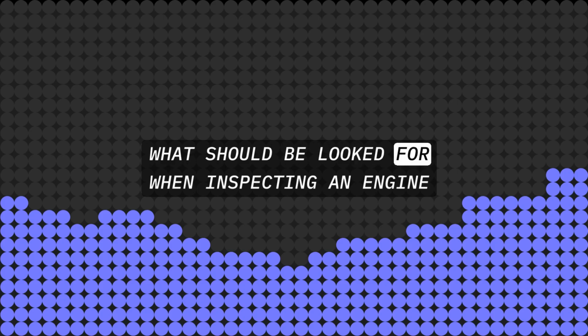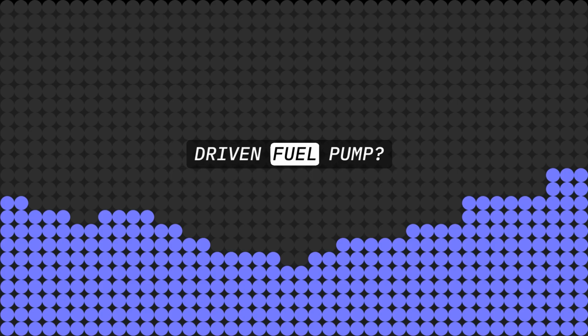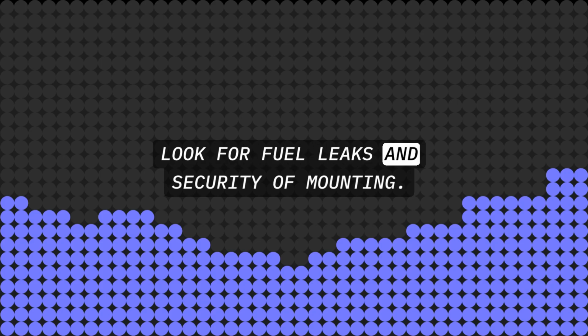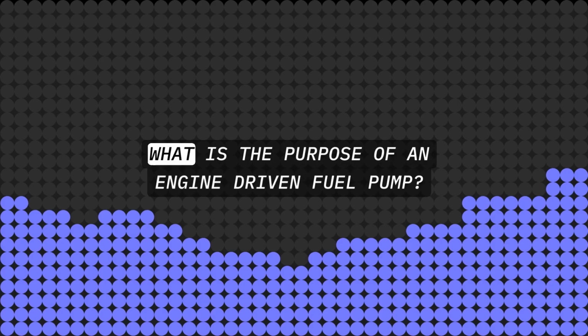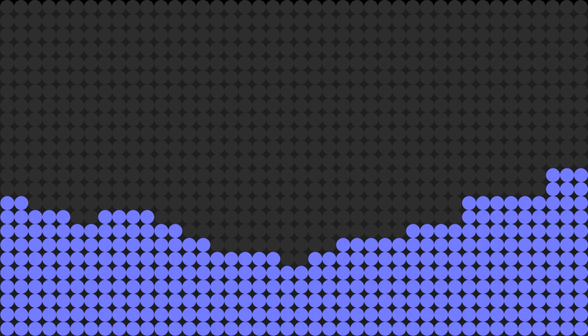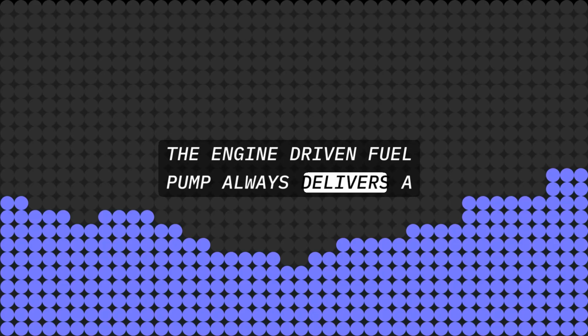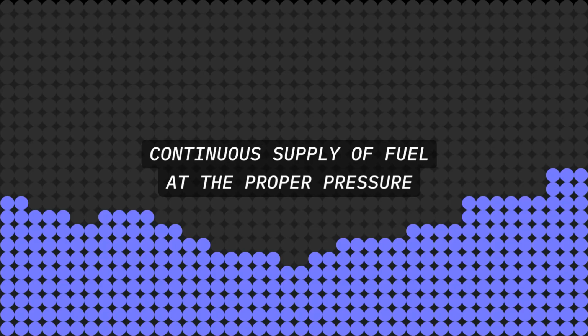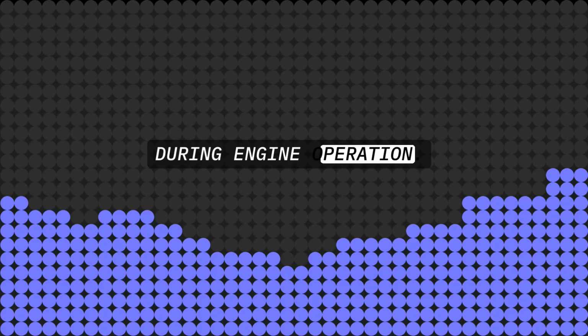What should be looked for when inspecting an engine-driven fuel pump? Look for fuel leaks and security of mounting. What is the purpose of an engine-driven fuel pump? The engine-driven fuel pump always delivers a continuous supply of fuel at the proper pressure during engine operation.